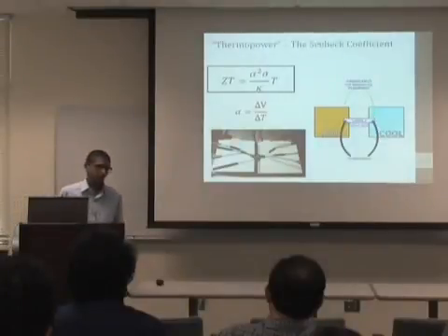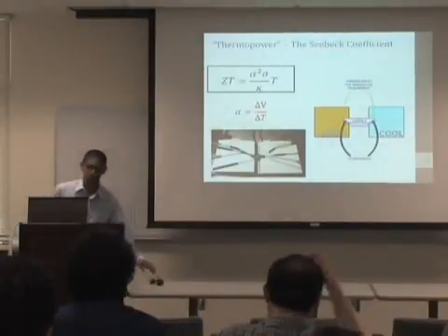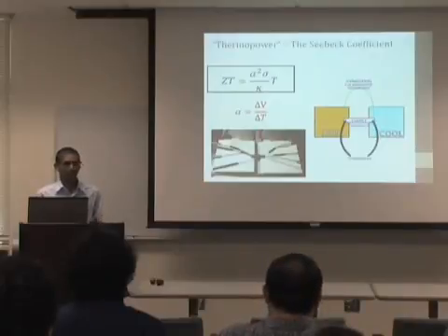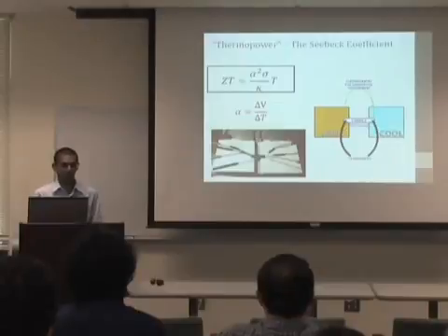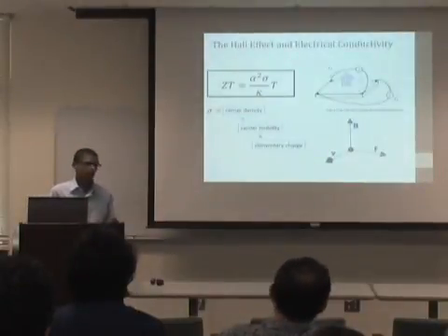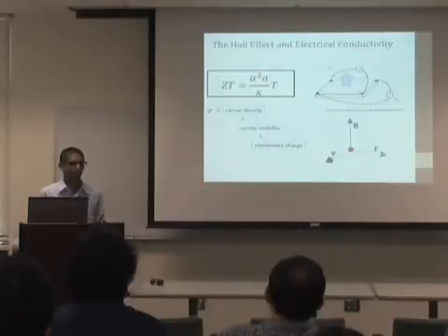Now, after we grow our material, we characterize them, and one of the measurements we do is called the Seebeck measurement. We basically measure a voltage that is driven by the temperature difference. So we use a multimeter to measure the voltage, and we use thermocouples to measure the temperature difference that's driving that voltage. And then we do a simple 4-point measurement to find the conductivity of our material. And then we do something called a Hall measurement to find our carrier density.